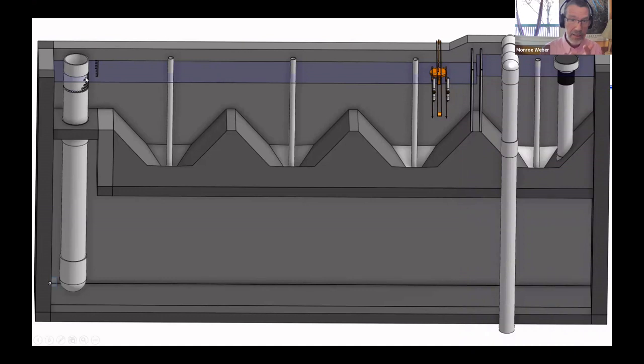The next piece is the water exiting the place where the sedimentation is happening, goes to this linear flow orifice meter. This is a device that was specifically designed to get a linear relationship between flow rate and the depth of water in this tank, and we'll talk more about that later. So that's all happening inside this entrance tank.